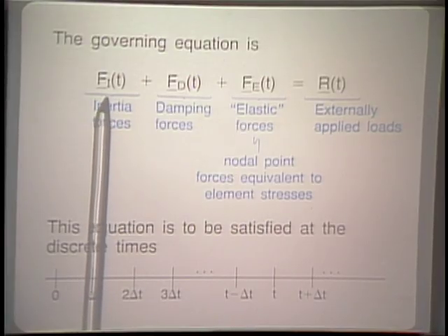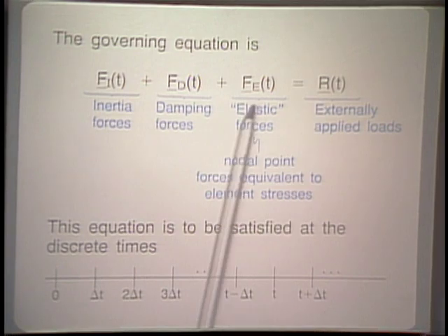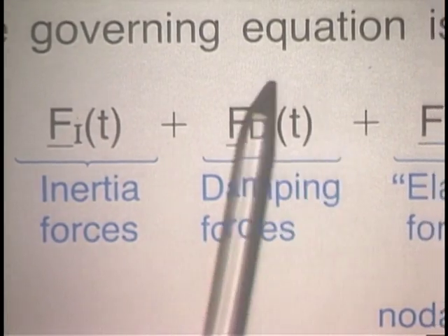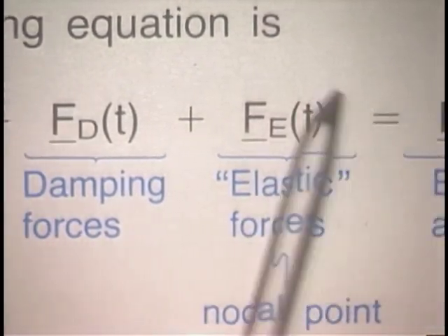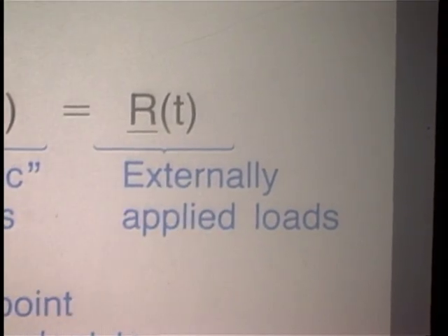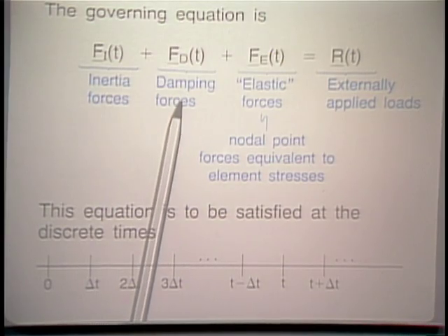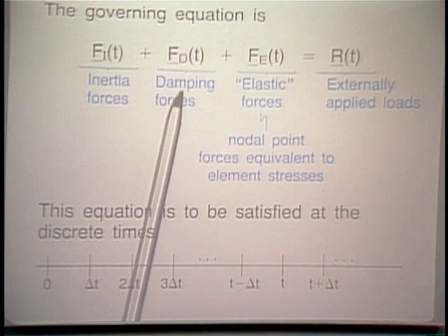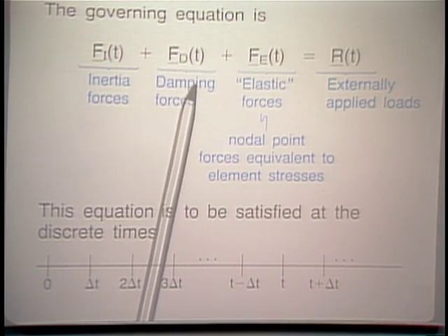When we want to solve the finite element equations in nonlinear dynamic analysis, we recognize that basically we have to operate on this set of equations. Here we have the inertia forces, the damping forces, the elastic forces, and the externally applied loads. The inertia forces and damping forces, well, you know them quite well. They are written in terms of mass matrices, damping matrices, accelerations, velocities.